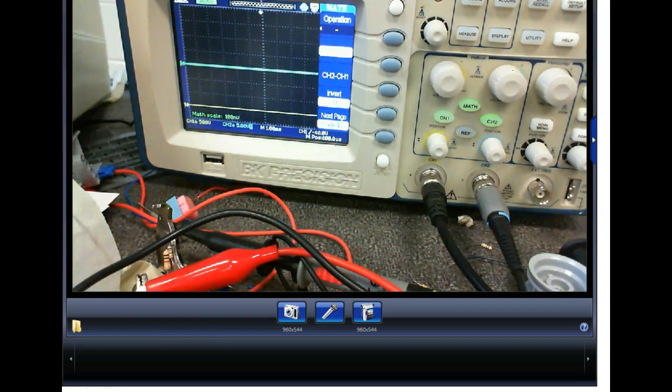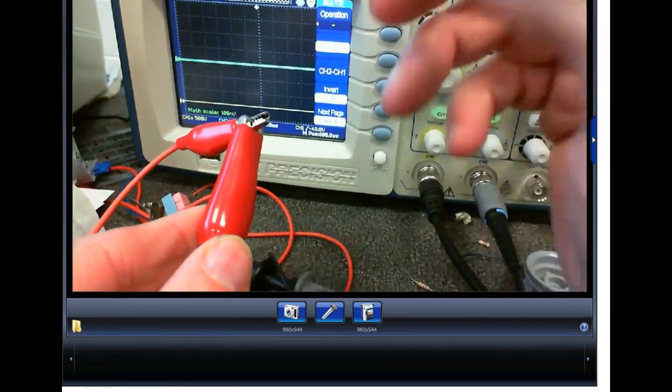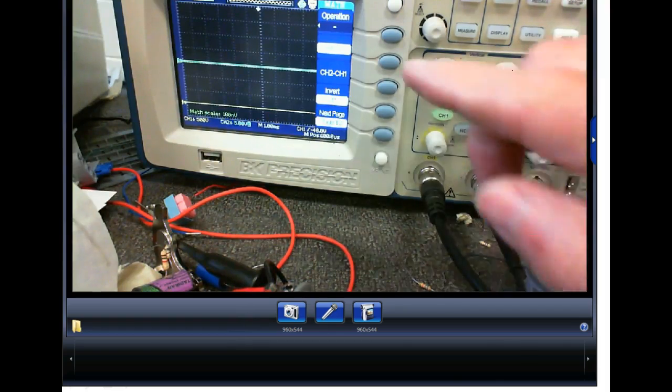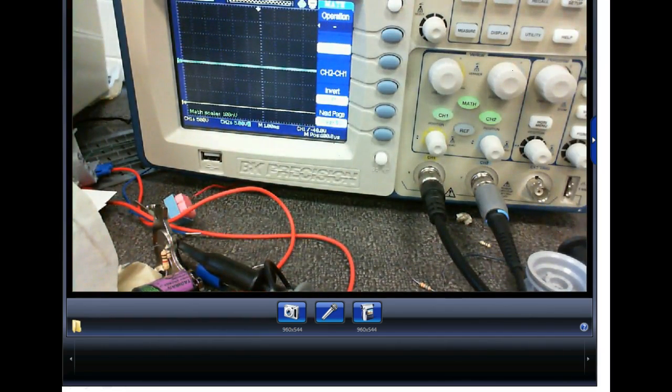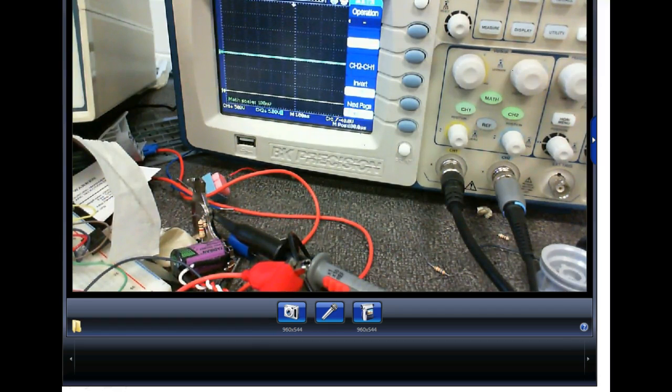So we'd tell it to subtract channel 1 from channel 2, and then I would probe through with these red leads. So I could put the red leads anywhere I want to. So I could put it across a resistor. And my scope would subtract channel 1 from channel 2, and it would show me the results. This scope actually brings up a green chart that shows you the math operation. An analog scope, you can't do that. So if I want to probe inside a circuit with two of my leads, then what I do is I just tell my scope to do what? Subtract the 2 channels.